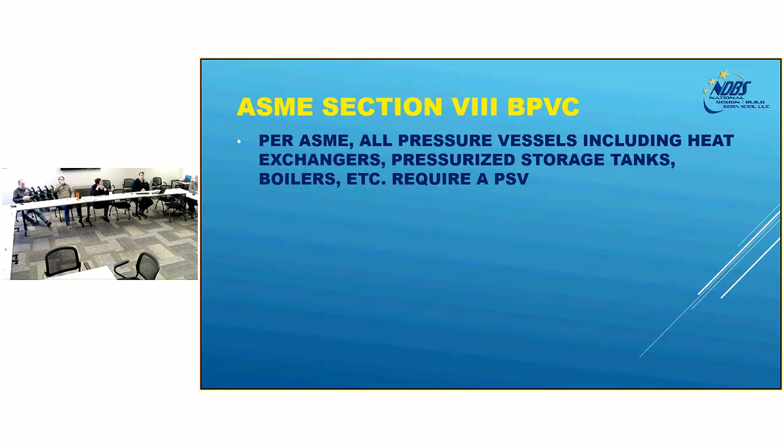Quick question. Back on the MAWP being determined by the design engineer, is that the engineer designing the pressure vessel itself, not the person ordering? It's the person ordering it. It's the design professional responsible for the process. They can define it above the calculated minimum code value. A lot of times it comes down to availability of the vessel, because you can buy a U-stamp vessel that's 125 PSI. It's already been tested. It's in stock. You're not going to find one that's a little off based on your calculation.